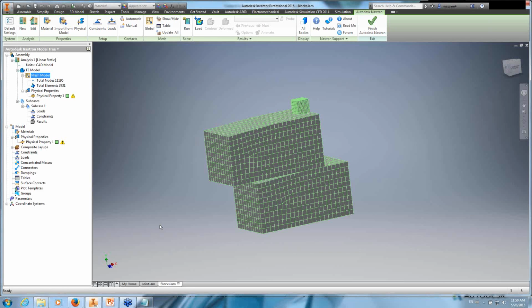Now, when defining a manual contact pair, there's the option to do automatic. That'll search out all the surfaces there if you don't define any. That may be a good approach, but at the same time there's not a good way of seeing exactly what's being defined there. So the better approach, in my opinion, is to go in and make sure you get all those contact pairs defined, and that way you can set them up in the manner that you're looking for.